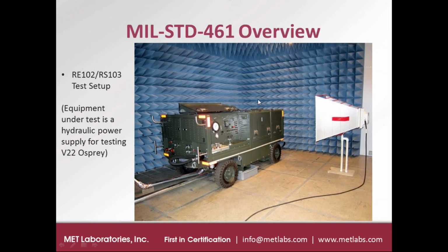And this was an interesting test and gives an example of one of the challenges that we have to overcome when doing EMC testing, because this was a diesel-powered generator. So we had to figure out a way to exhaust the diesel fumes out of the chamber and then out of the building, but we still have to maintain a shielding effectiveness of the chamber so that we don't have any ambient leaks.